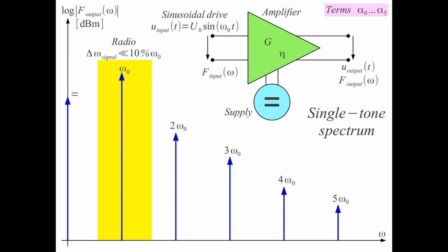We have similar effects also in optics, in optical fibers. In optical fibers, the important bandwidth of a signal is quite limited. Not because of the fiber, because the fiber is quite broadband, but because the nonlinearity in optics is distributed, and with the phase mismatch the only terms that we actually get at the output are those close to the input frequency. So it's very difficult to generate the second harmonic, the third harmonic, fourth harmonic, and so on in optics, because we have to deal with phase mismatch, because the nonlinearity in optics is distributed.